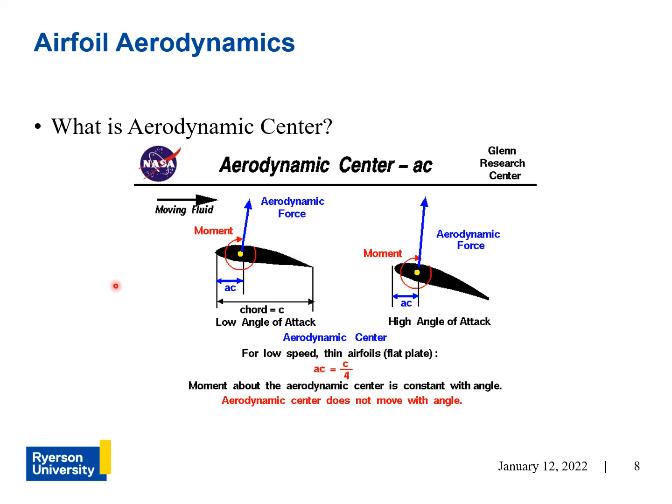The act of balancing the moments on your glider, aka having a 0 net moment, is called trim. And that's the main reason why aircraft have tails: to counter this inherent pitching moment produced by the airfoil.